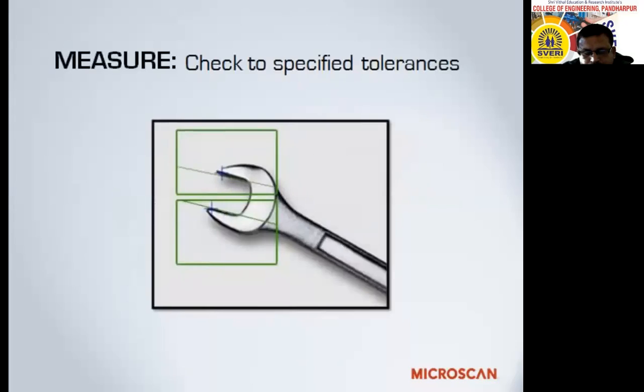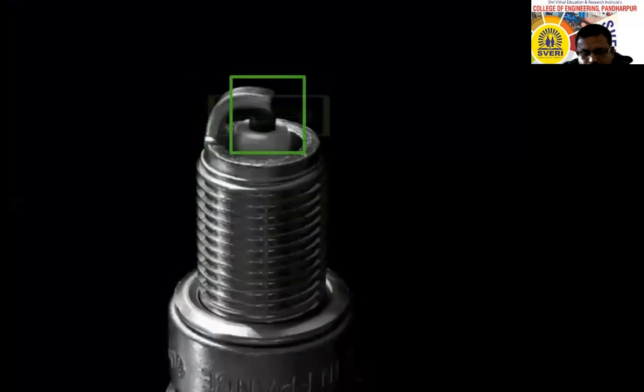For example, something we've been doing for years with machine vision is measuring the gap in spark plugs. As you may know, this gap needs to be a certain width, or the car won't run as well. Therefore, this gap measurement is an extremely critical spec for the part. We can use a camera and measure the spark plug gap by machine. This eliminates the need for a person to be there to measure and adjust the gap manually. We can automate the process and do it more quickly and accurately.